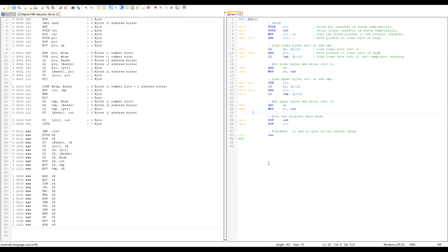Hey, I see you stuck around to the end of the video, so I'm gonna explain this Proc 16, and if you already paused the video to figure it out, good for you. Let's get to explaining it. So first off, what you want to do is push the data to the stack. So the upper half of the B input, followed by the lower half, followed by the upper half of the A input, followed by the lower half.